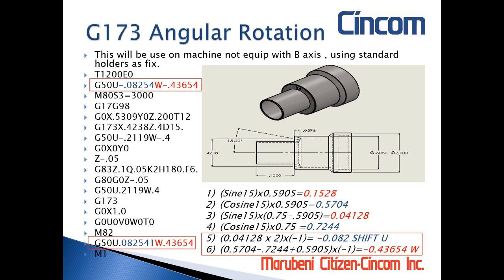So I want to dive in at the same angle, which is 15 in this case. So what I did is make a right triangle, and my real point will be Z.4. I gave my right triangle 0.2, so I make the calculation times 2. The adjacent will be times 2. So I add, so it will be a little bit above, just to make sure that I'm not colliding with the stock or something.